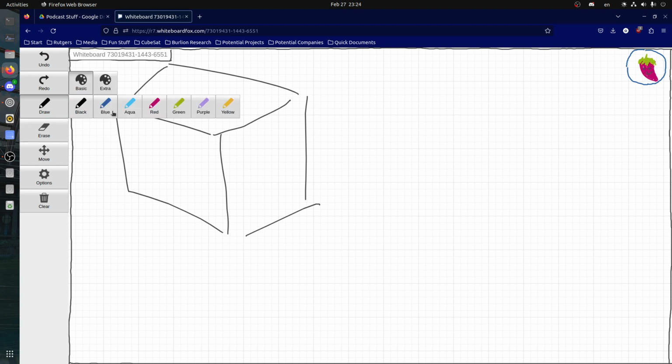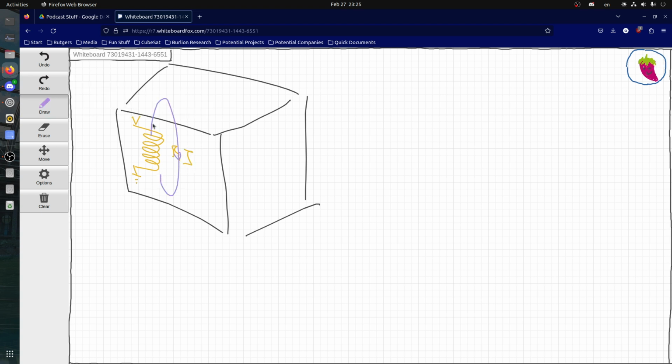The next one is a magnetorquer. A magnetorquer is a simple device. It's just a solenoid, and you decide how much current is going through it. So you apply some voltage. It has some resistance, usually small, and because of that, there will be some current that goes through it. This current will generate a magnetic field, which goes like this. The control that you get is very small, but it is not zero. So if you have a very loose pointing requirement, where you just need to point straight north or straight south, or some variation in only one direction, then this can suffice.